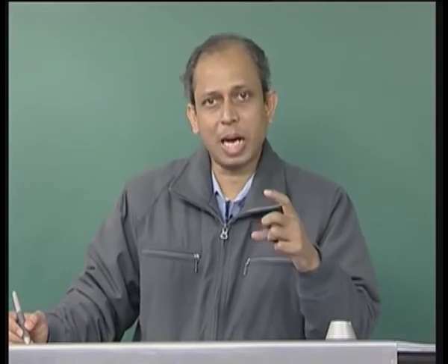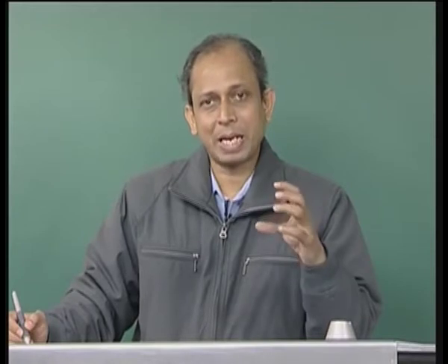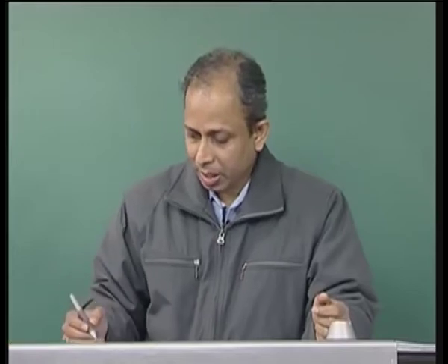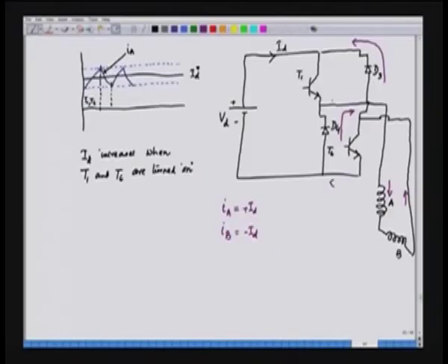And when these two diodes are turned on, a negative VD is applied across these two windings. Okay. So, we can see here that earlier this point was positive. Now, we see that when D4 is on, this terminal, the terminal of phase A, this is phase A terminal, and this is phase B terminal. Phase B was earlier positive because T1 was conducting. When D4 is conducting, A becomes negative. So, it means there is a tendency to reduce the current.